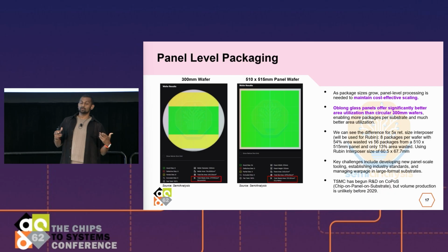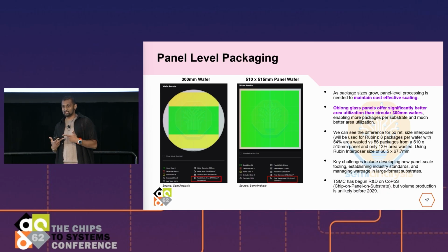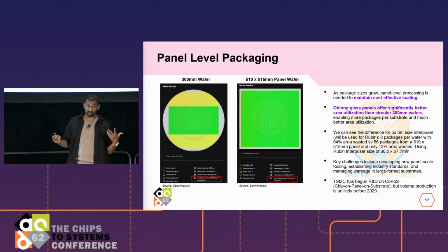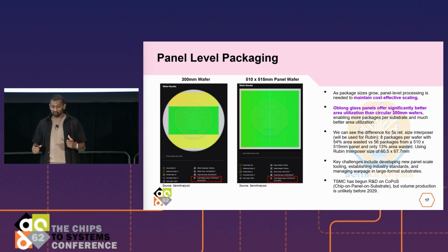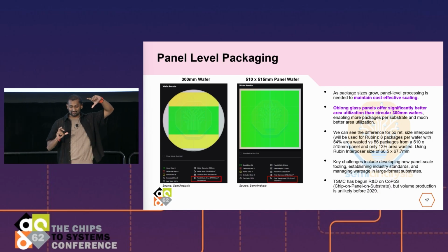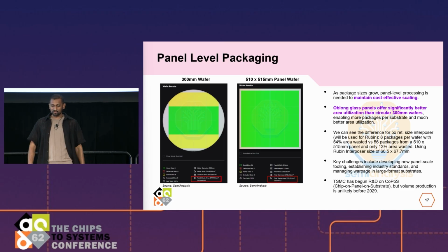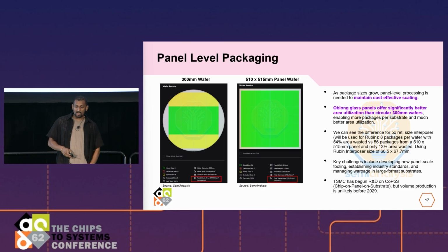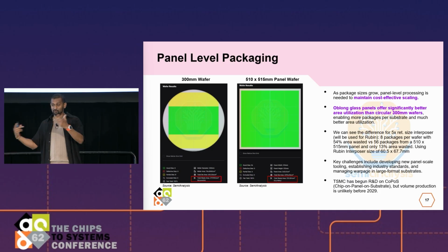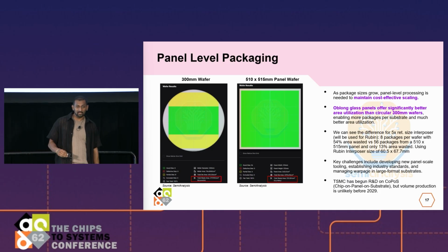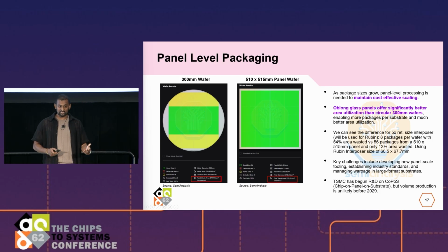of packages, right? With these packages getting 5x, 6x, 8x reticle sizes in design, fitting them on a 300 millimeter wafer is kind of impossible, right? Fitting very large squares on a circle, tough. So the industry is moving to these large format panels, which have been used for substrates, but not for advanced packaging. And Intel has panel level format work. TSMC has panel level format work.